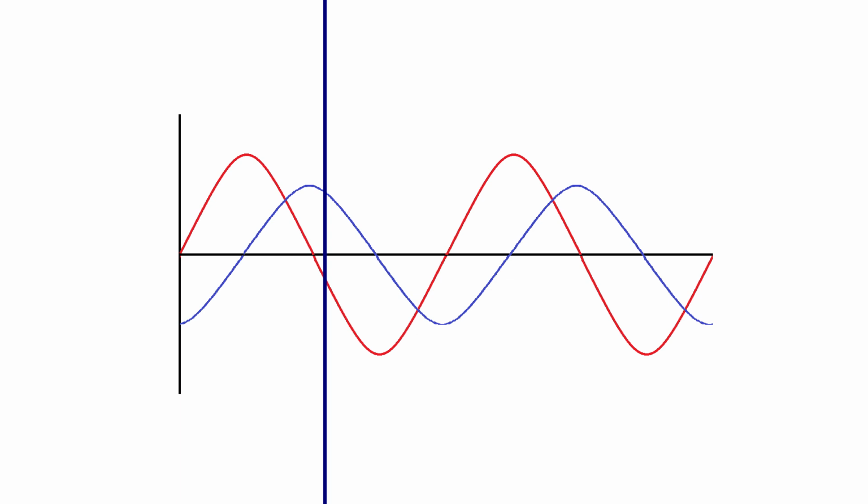Okay, so here we have a negative voltage and a positive current, which wasn't possible in the light bulb, but now it is, because voltage and current are no longer in phase. And so, now we have a negative number multiplied by a positive number, so we get a negative number for power. That's weird, right? What is negative power consumption? Well, if you think about it, negative power consumption means that we're supplying power.